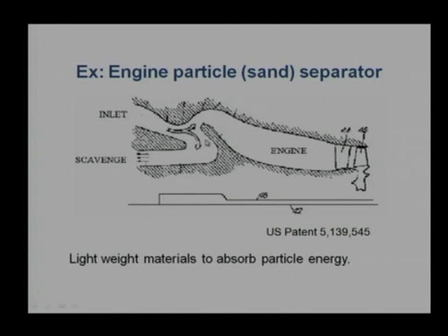This particle comes and impacts it, so this will be slightly flexible. If a system is flexible, it will not wear out very fast, unless the fracture occurs over this cross section itself. If the fracture occurs at this cross section, that is fine, but that will be a fatigue problem, and we can design from the fatigue point of view. Maybe we can design this system for more than 10⁻⁶ cycles, 10⁻⁷ cycles, or 10⁻⁹ cycles. That depends on what kind of design we require and what the life of the system is. Many times when it comes back, we can replace this material also.